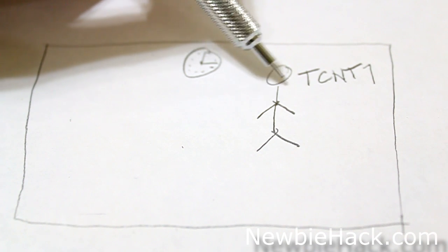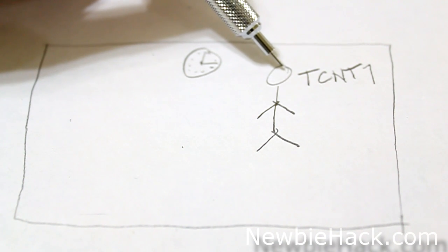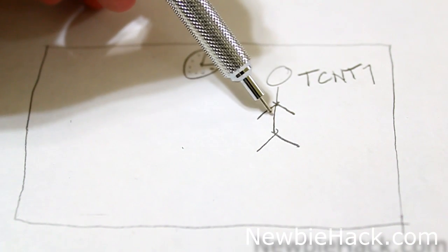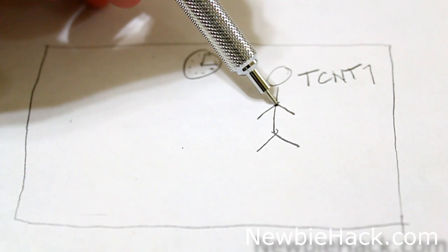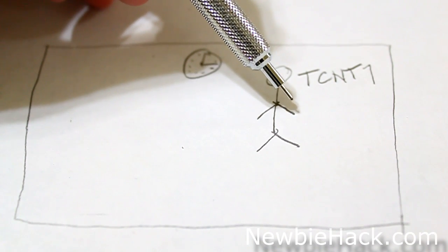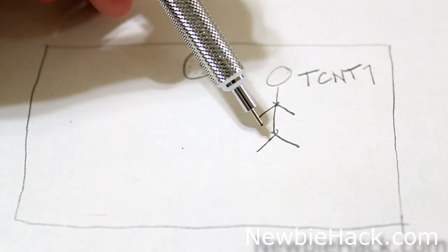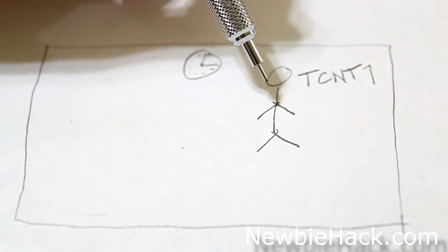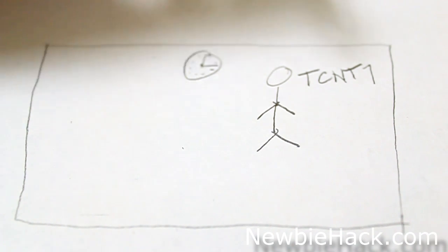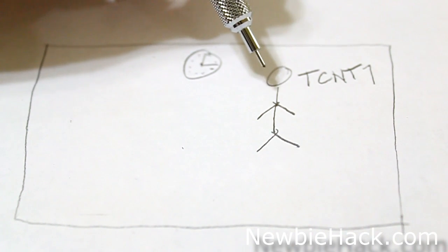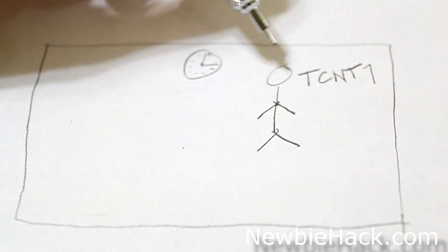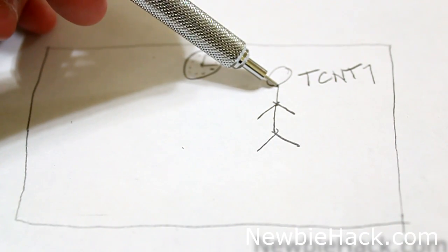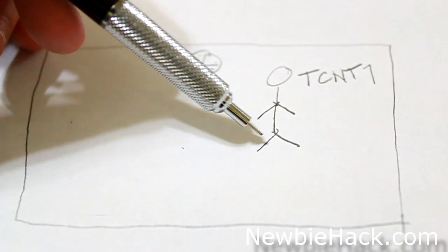However, Mr. TCNT can only count up to 16 bits of binary numbers. And 16 bits, if you remember back, talking about the binary number system, is actually 65,535 in decimal. In other words, he wouldn't be able to count up to 1 million clock cycles. So you're probably wondering, how would we be able to get the timer to count in seconds? I'm going to show you one way to do that without having to count up to 1 million. And there's also something called prescalers that I'll introduce you to later on.